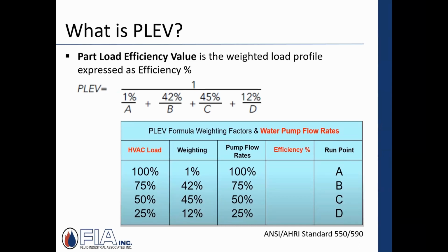When it comes to the selections, when we get into the software, one of the items I like to pay attention to, obviously we're looking at that duty point efficiency, but we have to keep in mind that duty point efficiency is for our greatest load. That's our design day condition. We also have to consider how infrequently we're really going to be operating at those conditions. Pretty rarely. So something that's a bit more true in terms of what you will see for efficiency is a weighted efficiency.